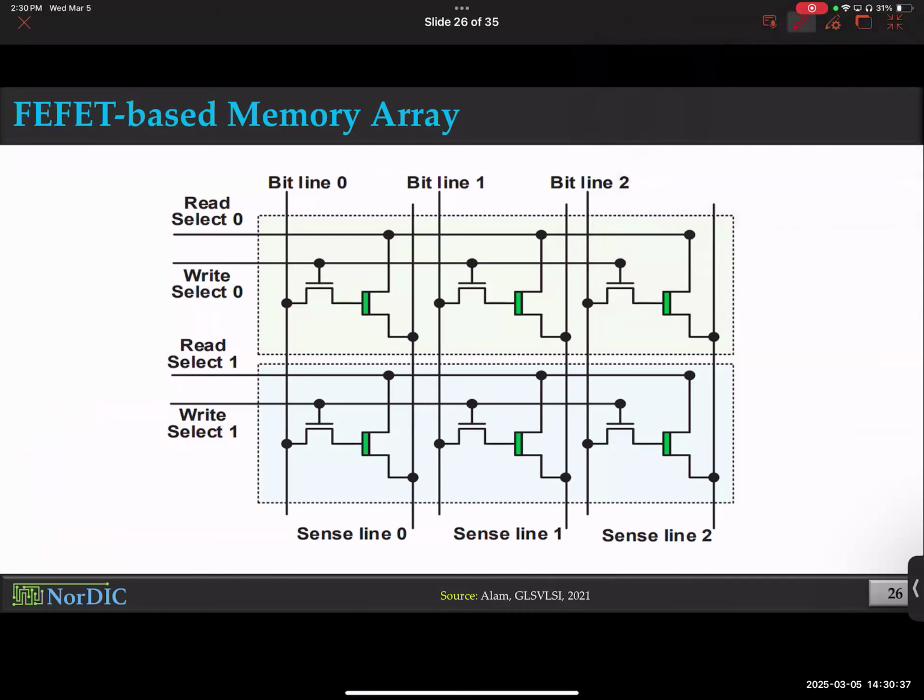I guess all good so far. The other uniqueness here is that for all the other memories, the memory element, for DRAM it was a capacitor, for STT-MRAM it was an MTJ. And you will go through others, PCM, resistive RAM, memristors, they will all be similar to this format, 1T 1R.